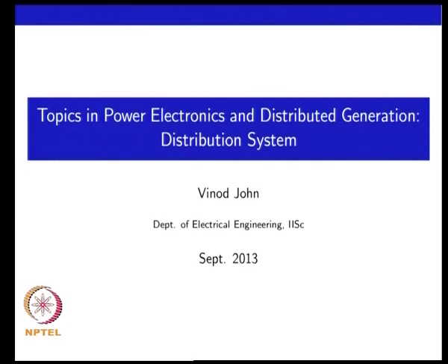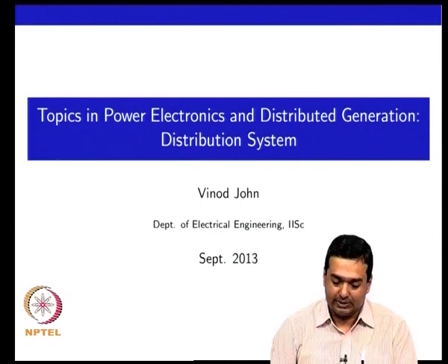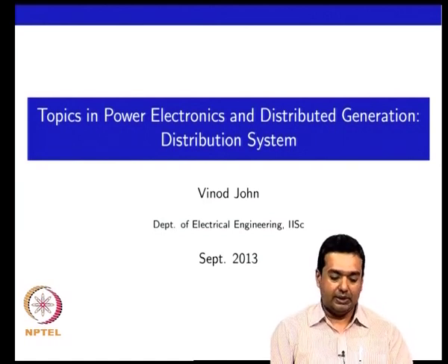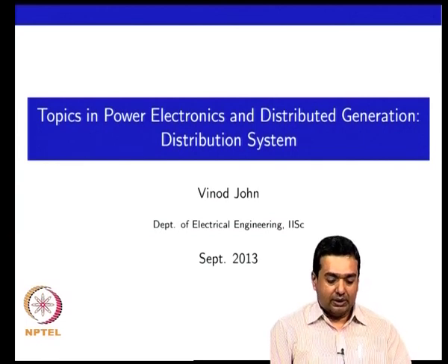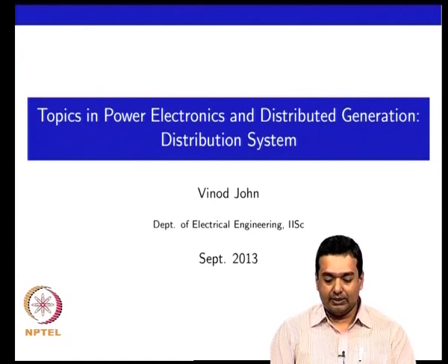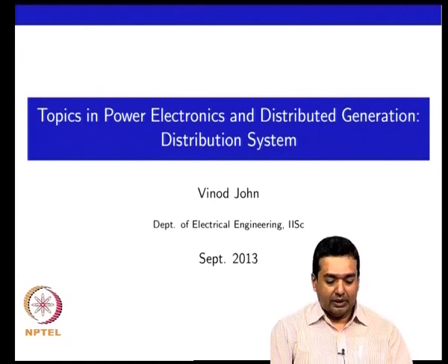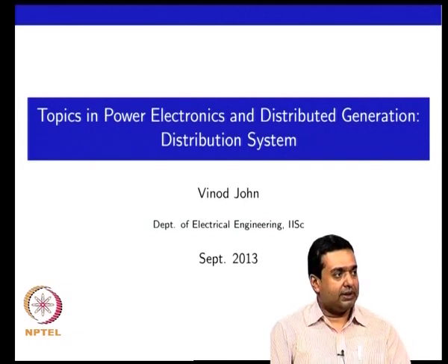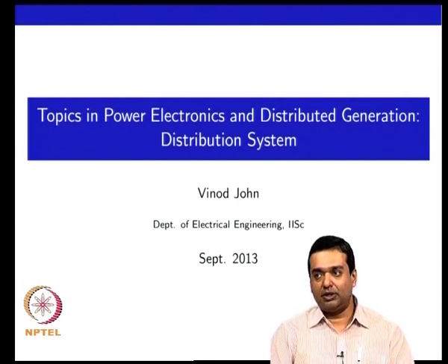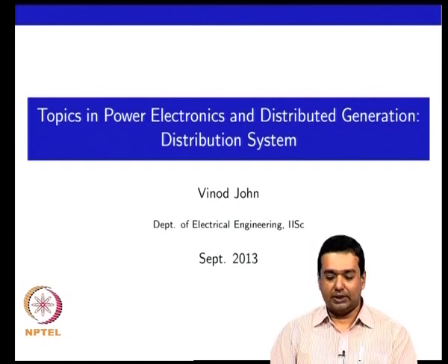We have been talking about active anti-islanding in the class, and last time we looked at the relationship between power and voltage. We modeled the feeder as a parallel RLC resonant circuit, and then looked at how you could add power-voltage characteristics to cause the voltage to not have a stable operating point, but actually go out of the nominal range.